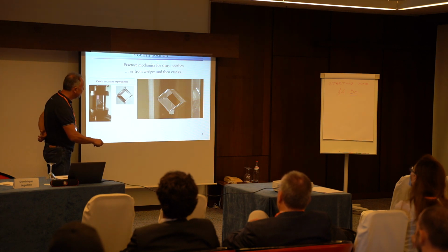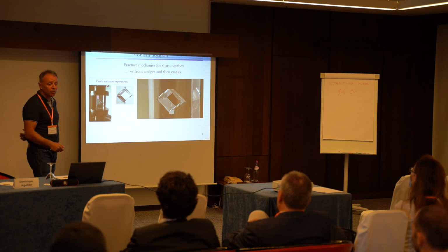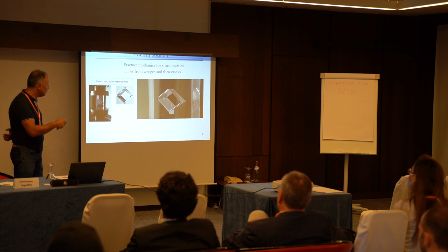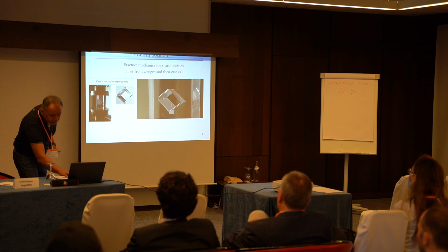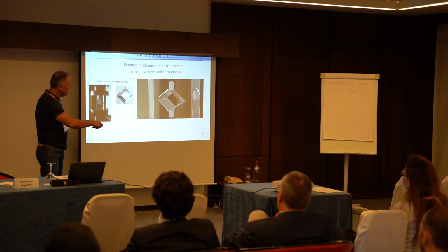Extensive work. People have focused for almost the last 20 years on the calculation of the stress intensity factor around a natural crack. And the remark number one that I'd like to make is that from a single experiment, which is here, a rhombus notch.